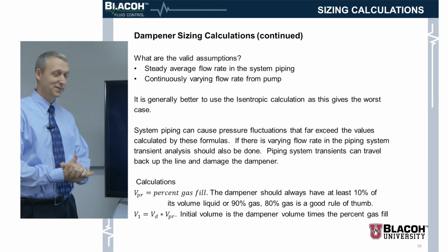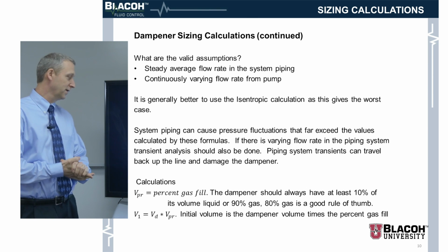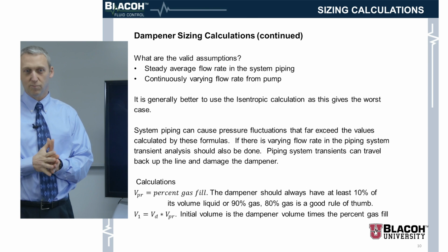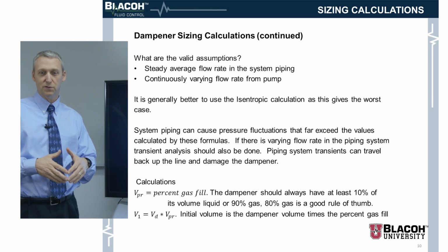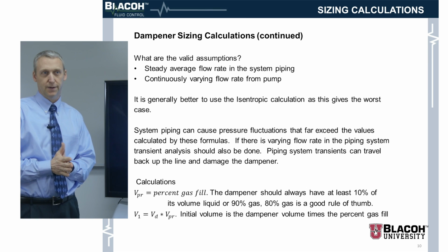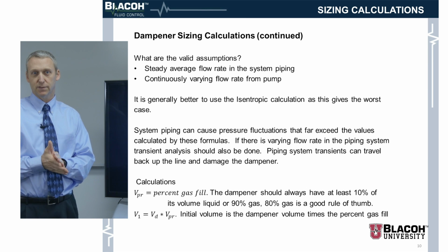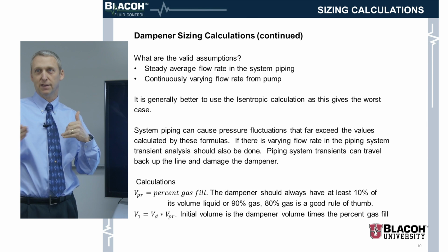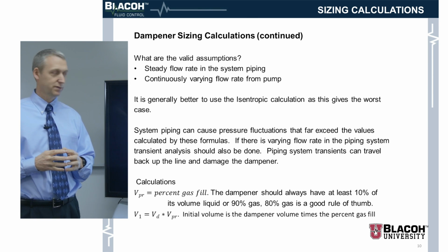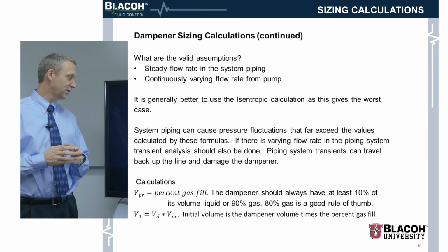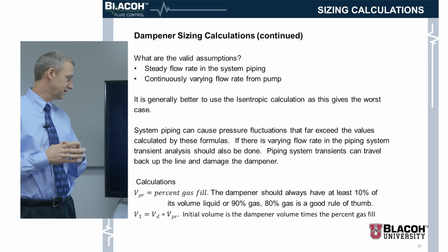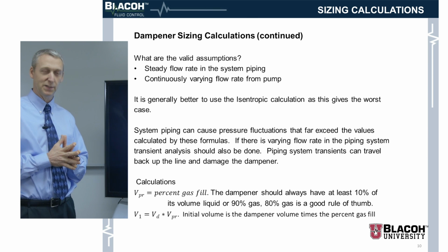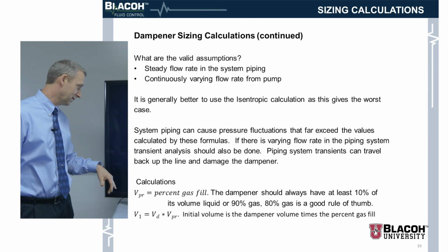And if it's too dampened, usually you're okay. That can be a problem also if you get too large a dampener, especially if it's like a metering application. You may get varying flow rates, which you don't want either. So the right size is good, and also too big is extra money and expense and all that. So we don't want to go there.